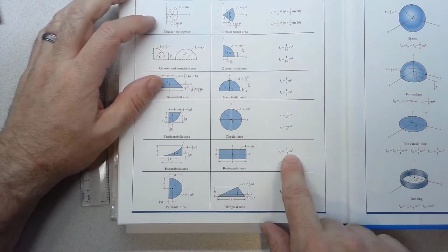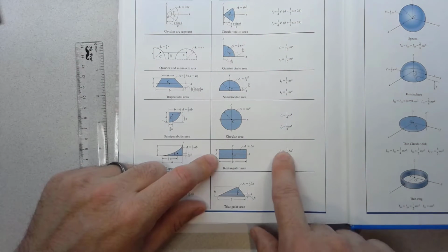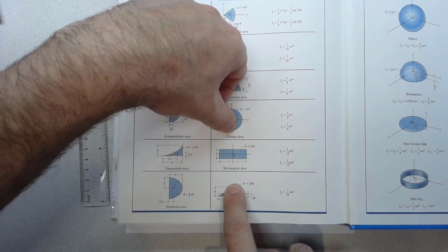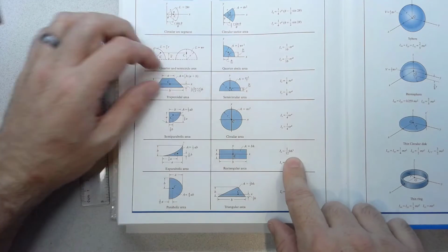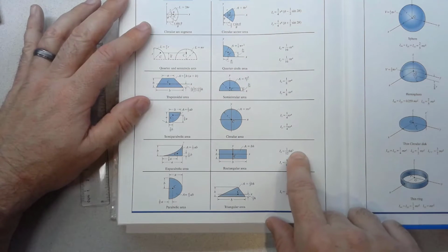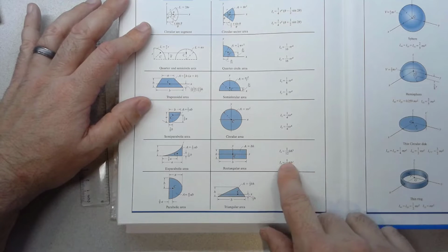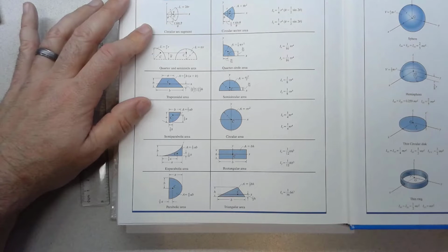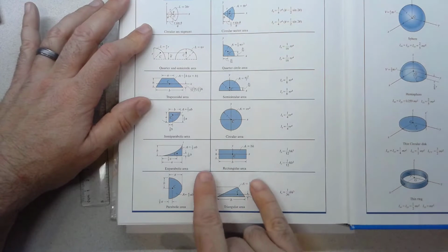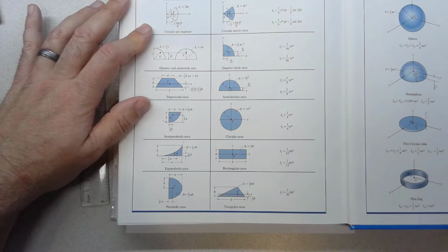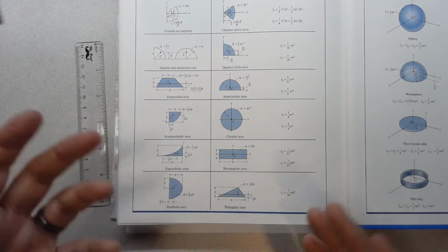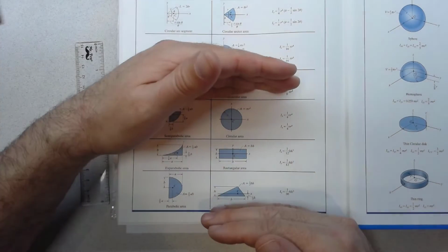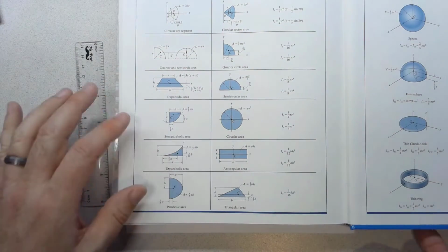So let's say you doubled the base, that's just going to double the total I, right? Whereas if you double the h, the distance away from the axis you're looking at, that's going to be 2 to the third, or 2 times 2, 4, times 2, 8. So you get an 8-fold increase for your moment of inertia if you increase height versus just a linear increase if you increase width. And that's why when you look at many engineering sections, they're basically maximized to put as much of the material as far away from the axis you're bending about as possible.